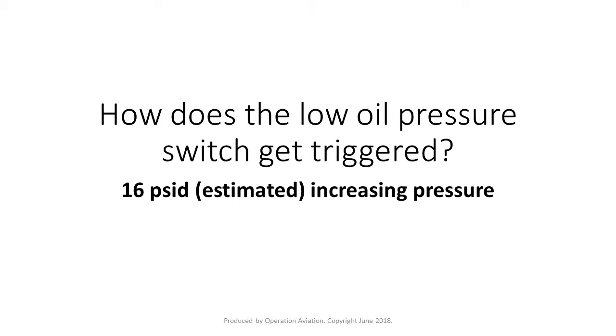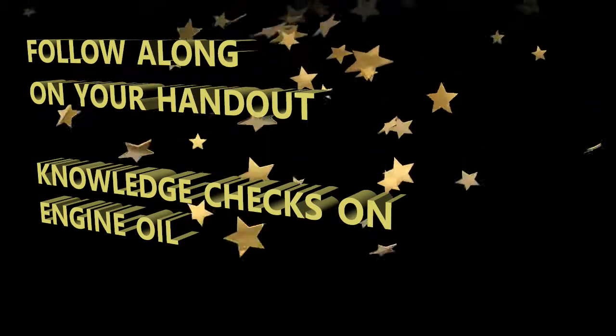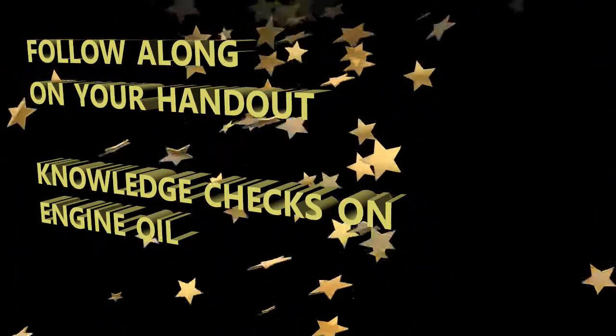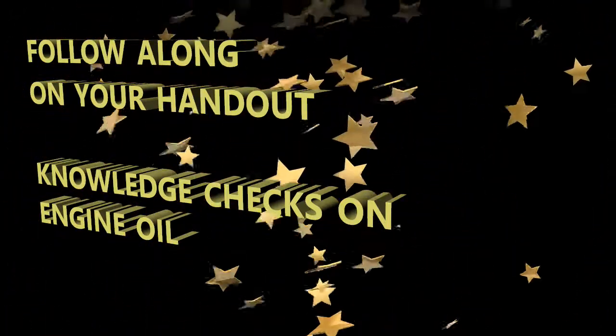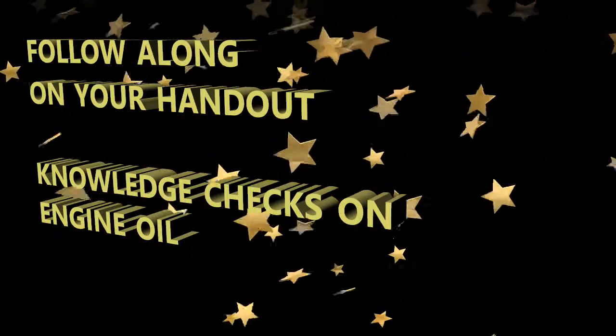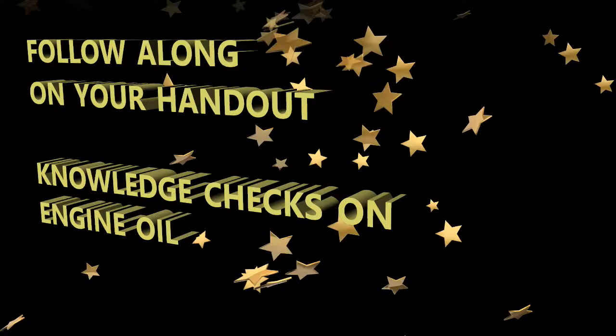How about this? When does the indication flash amber and the master caution light come on? I know I said 311 degrees Fahrenheit. If you see it on the test as Celsius, that's going to be 155 degrees Celsius. I hope you have a pen and paper in your hand right now.